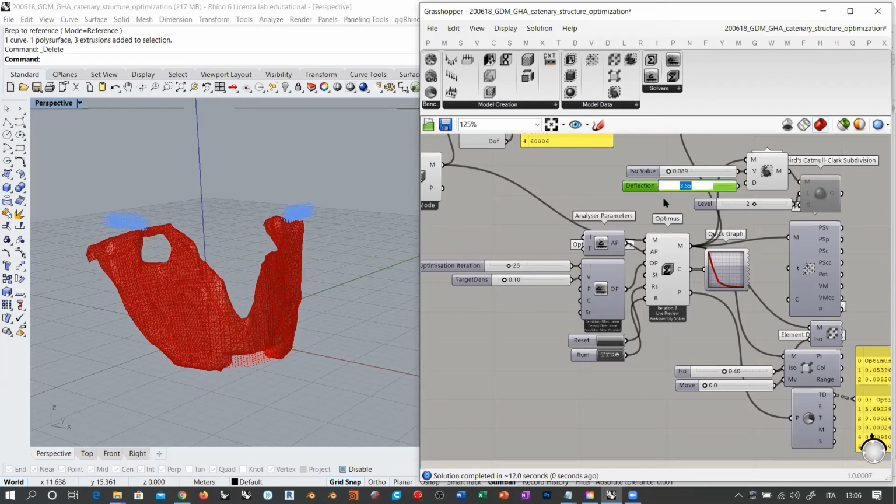Also, I'm not considering the value of the nodes, right? So it's totally, let's say, hypothetical, this study that we are running. But we already see something that is perfectly understandable. We have some stress flowing from the load area to the support area in the two regions. And this is also happening according to the curvature of our slab.